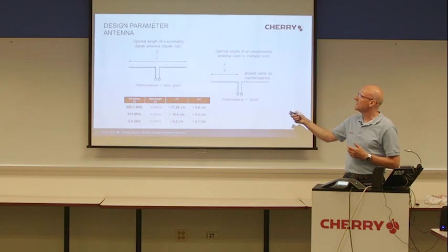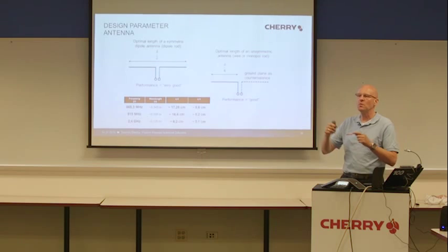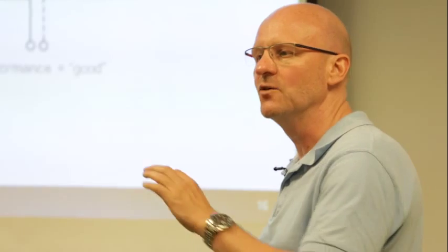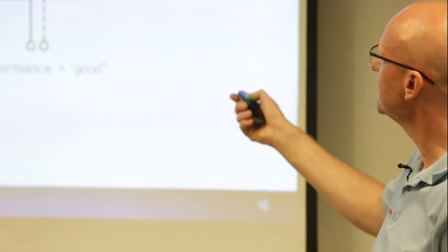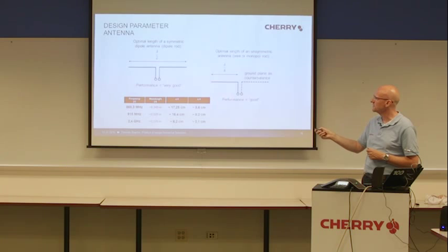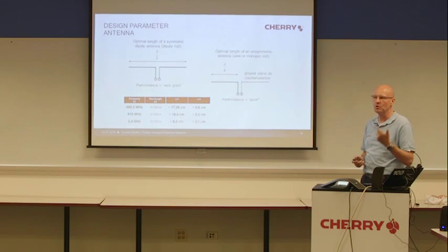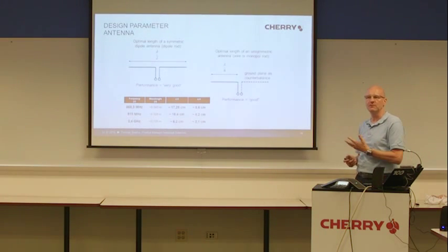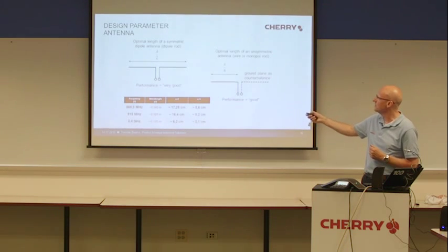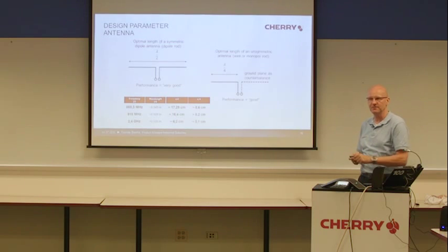And this is called a symmetric dipole antenna. So you would use two wires on your system. But you can also use a so-called unsymmetric antenna. So it's only one wire. The other pole is a ground plate on your PCB. And this is what we have, for example, in our rocker switch, in our module, in our snap switch, and also in our receiver. There is only one wire, and the other pole is on the PCB, designed on the PCB.